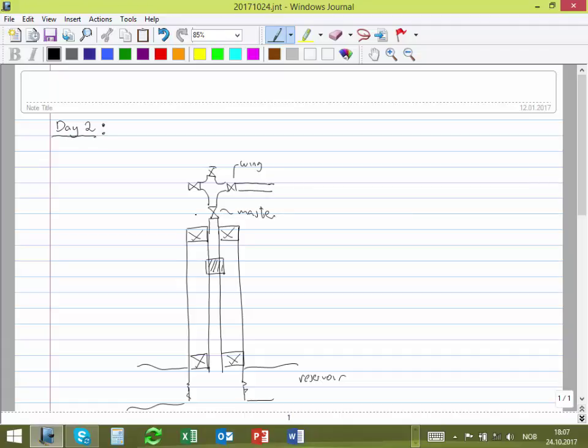All of these valves are on-off, okay? They are either open or closed. But there is one that we use to control production, which is the choke. And that one, depending, can be a bean choke, something that I change with certain frequency, or it can be an adjustable choke that I can actually control, that I can regulate.